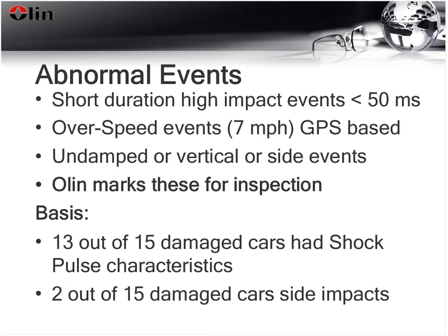You know, we've seen cars that have experienced 10G impacts and showed no damage, and we've seen cars with 5G impacts that had busted couplers, and we were wondering why. So essentially, over time, we've developed the following criteria to mark a car as needing inspection to look for damage.